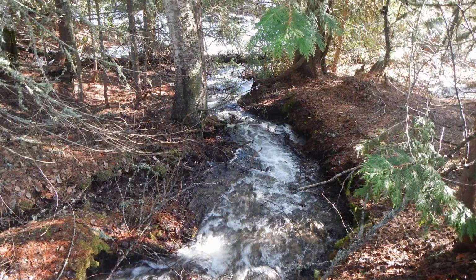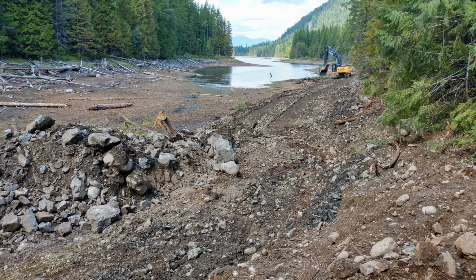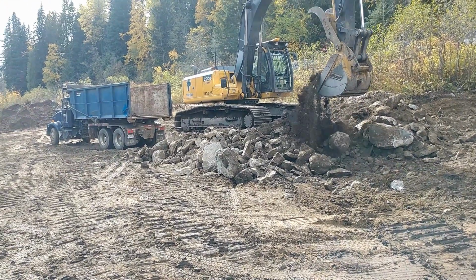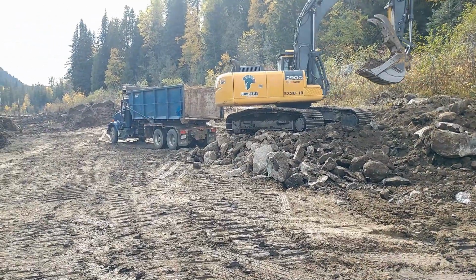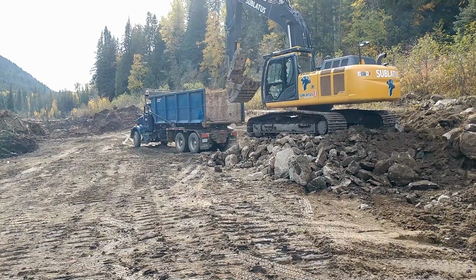We opened the siphon valve as needed to lower the elevation of water in Violin Lake so that Goodeve Creek would not flow over the area while the dam was being removed. Construction began with excavators removing and salvaging the rock that had been used to armor sections of the dam. The rock was placed in piles for later use in armoring the restored stream channel and the floodplain. We also used dump trucks to haul additional rock from the Cambridge Creek Dam that was being removed to the Violin Lake Dam site to use in armoring the stream and the floodplain of Goodeve Creek.